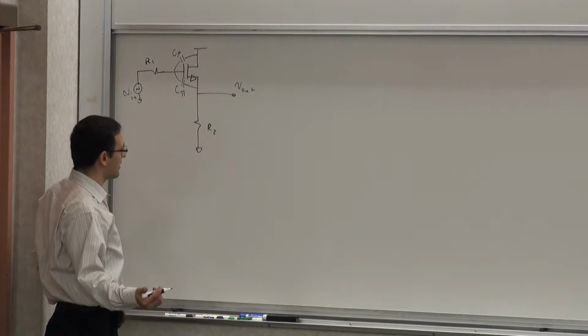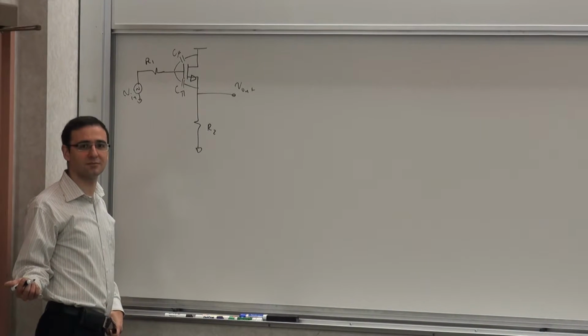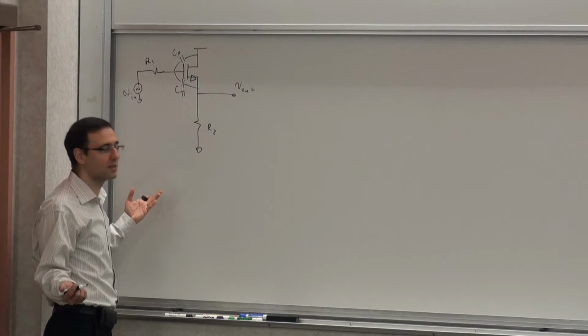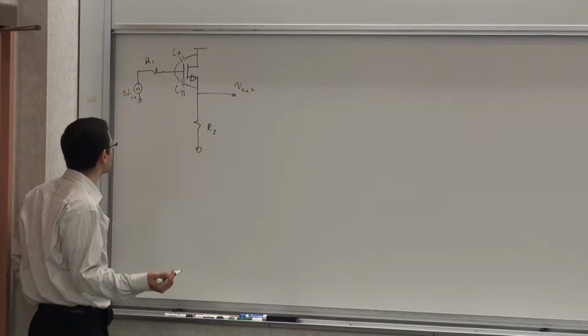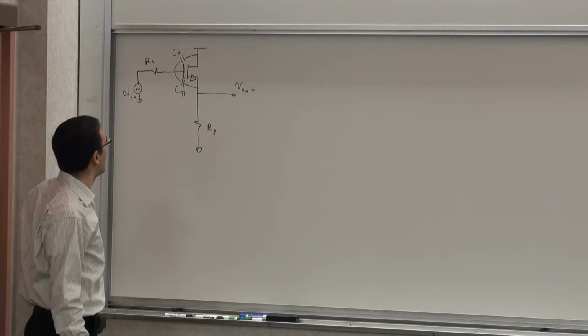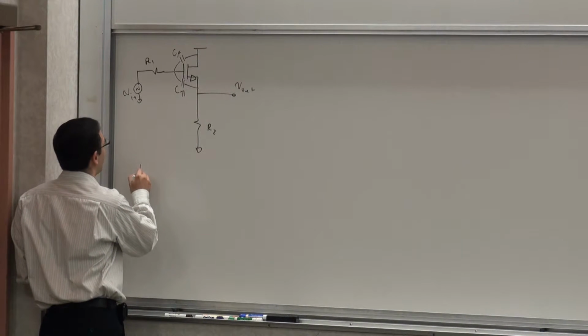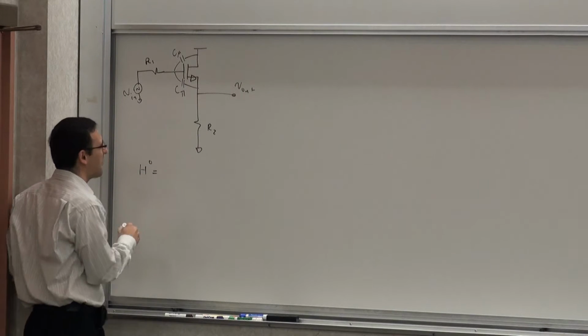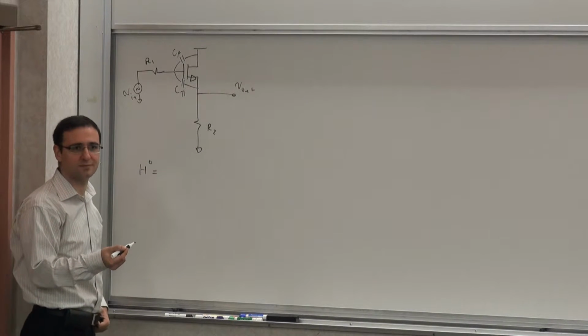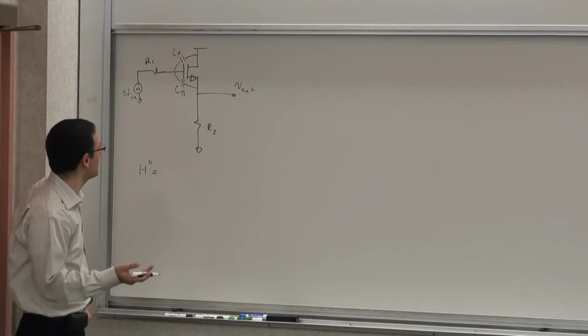So, left half or right half? Left half, because it doesn't change the polarity. It still remains non-inverted. Okay, so we already know that stuff. But if you wanted to know where they are, what do you do? Well, H0 is probably the first thing we calculate all the time. What is H0? H0, the low frequency transfer function.